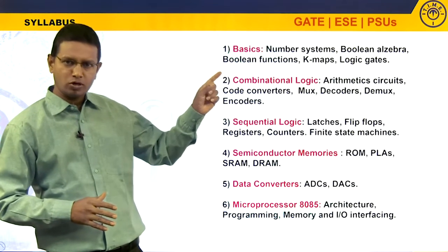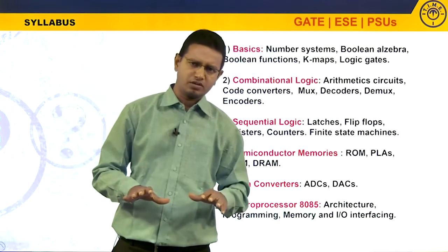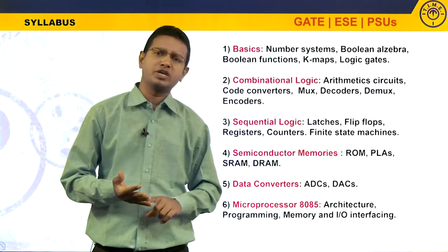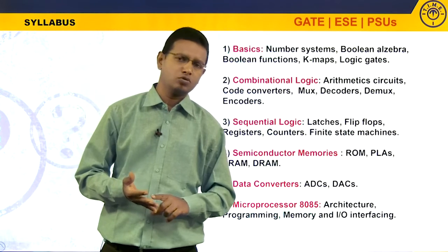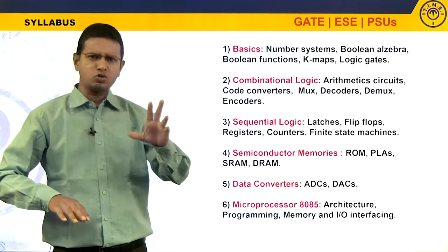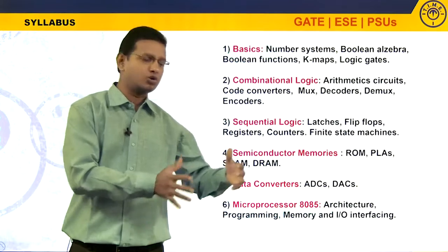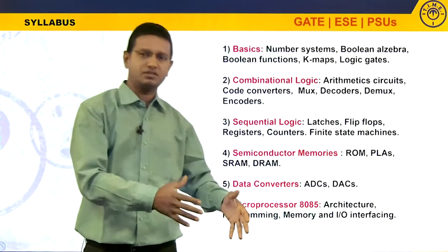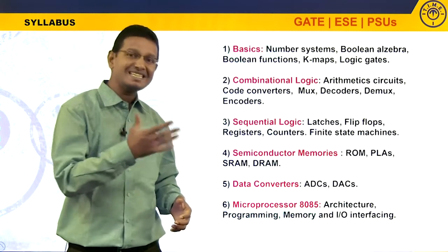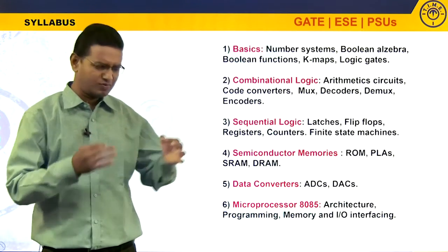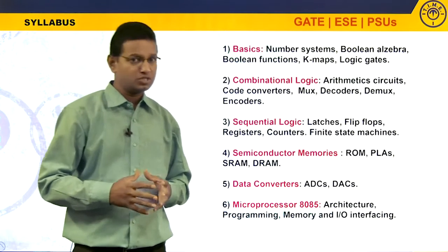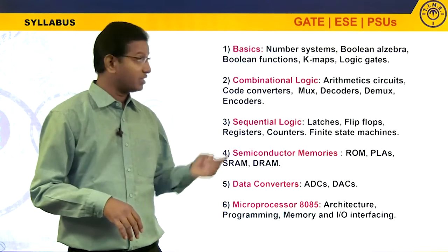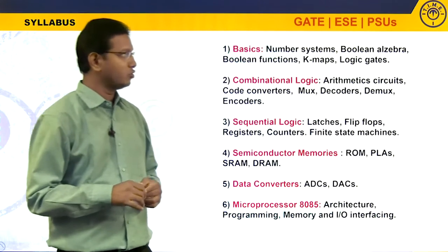Now, remember one thing, Boolean algebra is not a normal algebra. First thing, there will be no number systems in this Boolean algebra: no positive numbers, no negative numbers, no fractional numbers, no complex numbers, no numbers at all. There will be only two values, which are called logical values, logic 0 and logic 1. So, whenever there is a big equation, substitution is very easy, and we can easily validate that equation by simply putting zeros and ones, to see whether it is a correct equation or a wrong equation. This is one of the ways we can easily correct Boolean equations.